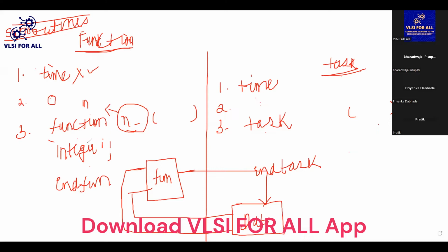So that is the reason we take help from SystemVerilog and use named blocks. The named blocks will be something like using a begin and an end, and at the begin and at the end we name them with the same name. With the help of that, we can declare variables inside the functions and the tasks.